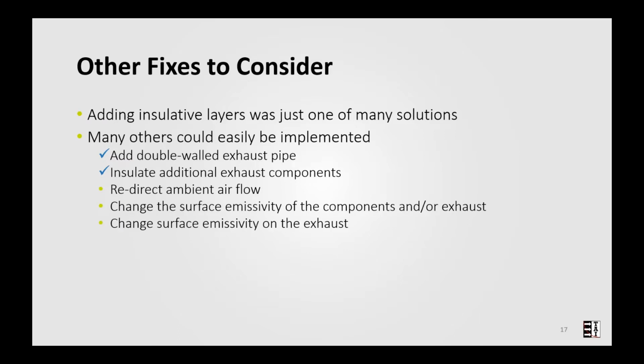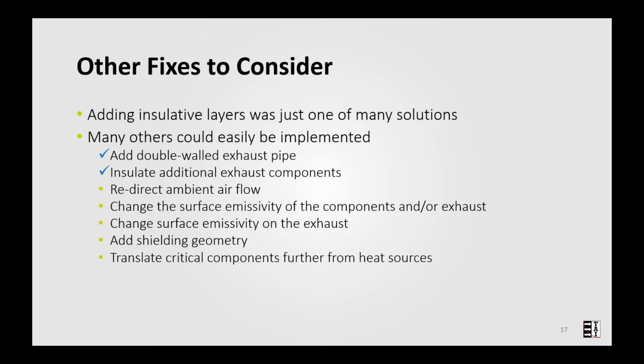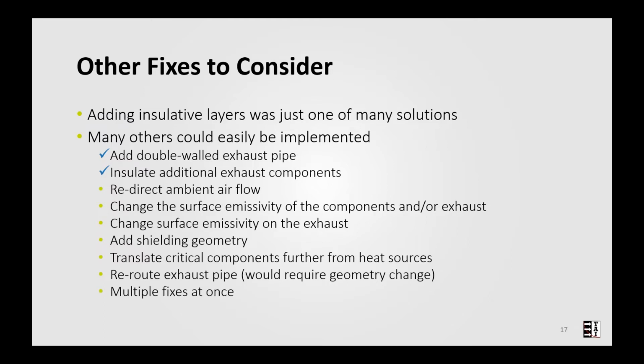Maybe they want to change the surface emissivity of the exhaust turbo so there's less outgoing thermal radiation to impact these components. Maybe we wanted to add some geometry for shielding between these components and the hot exhaust, or maybe we wanted to translate some of these components further away from the heat sources. Or maybe we wanted to reroute the exhaust pipe and implement new geometry. And maybe you wanted to assess multiple fixes at once. You could do all this in fairly little time.